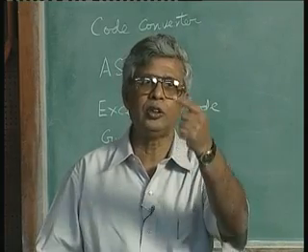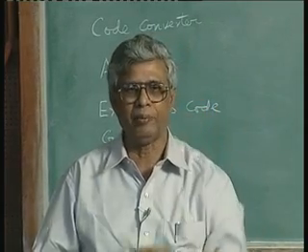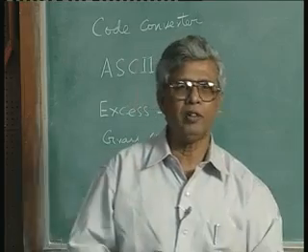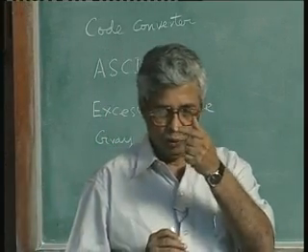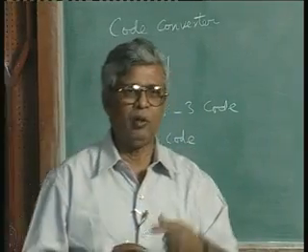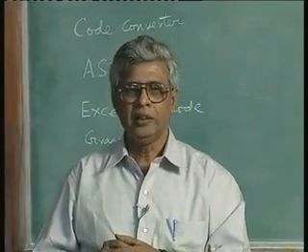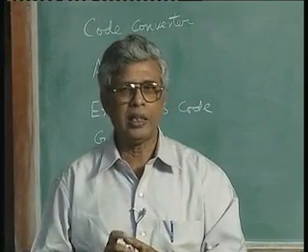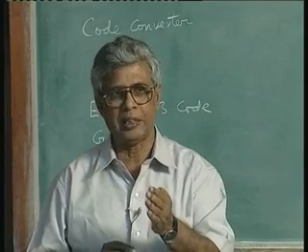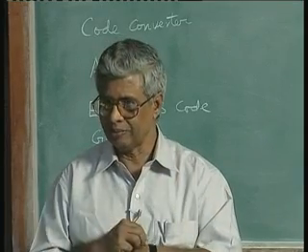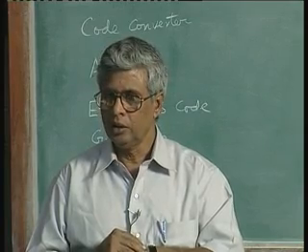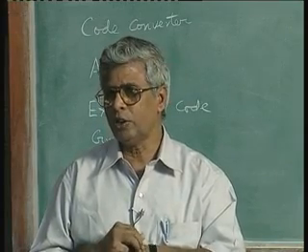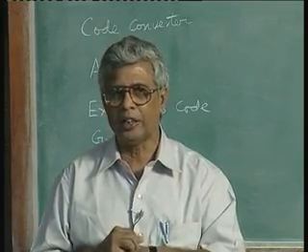Suppose I need to switch only one switch at a time. Whatever be the magnitude of the number, from one number to the next number, if I have to make only one switching, that reduces some activity. Switching activity represents speed of operation, switching activity represents power consumption. These are the things which you have to take from me now, but you can think of intuitively.